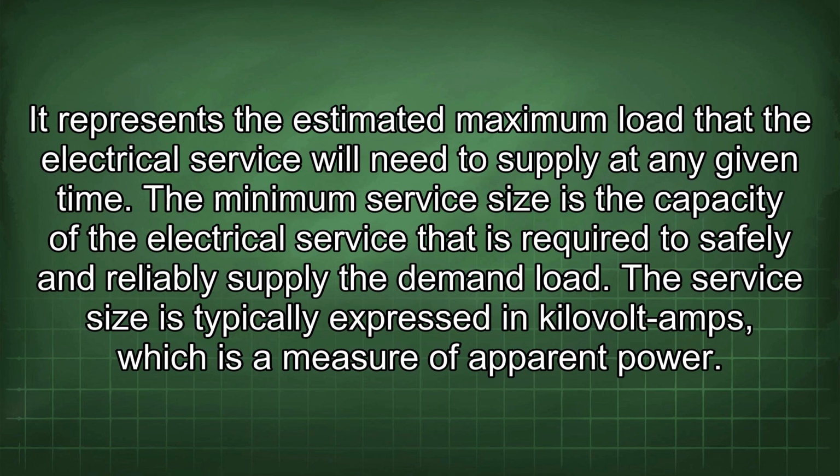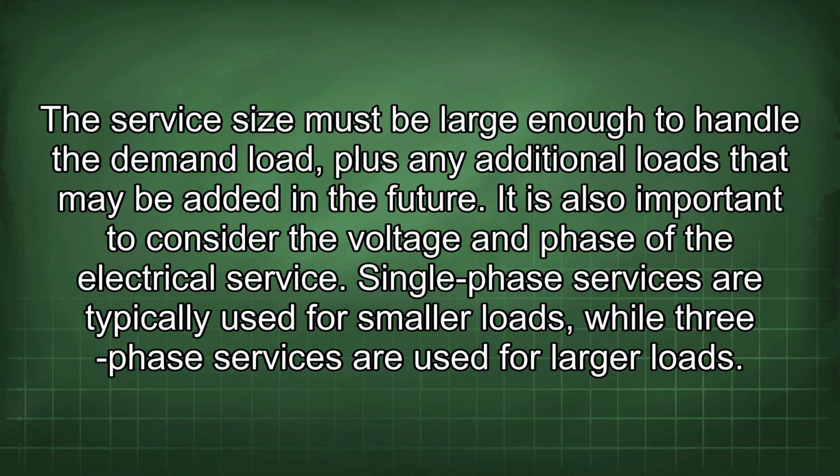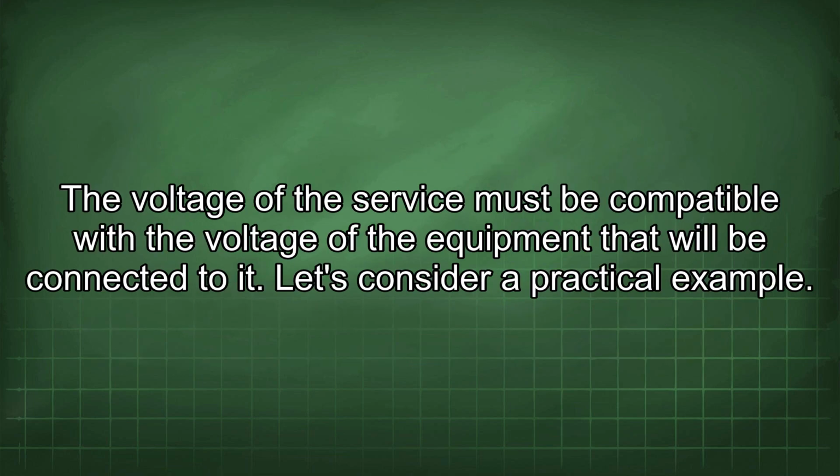The minimum service size is the capacity of the electrical service that is required to safely and reliably supply the demand load. The service size is typically expressed in kilovolt amps, which is a measure of apparent power. The service size must be large enough to handle the demand load, plus any additional loads that may be added in the future. It is also important to consider the voltage and phase of the electrical service. Single-phase services are typically used for smaller loads, while three-phase services are used for larger loads. The voltage of the service must be compatible with the voltage of the equipment that will be connected to it.